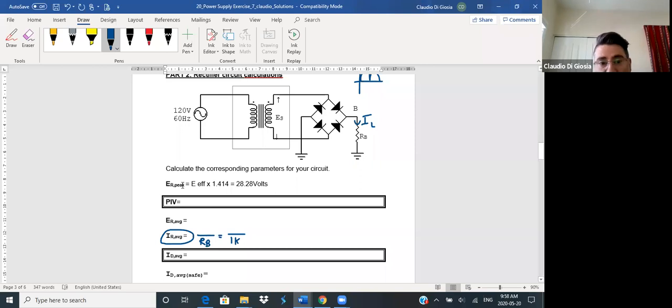So it's basically peak voltage, 28.28 volts. And that's basically when the current's going through and a diode is reverse biased, what is the maximum that it can block? Okay, and then eventually we're going to choose a PIV with PIV safe or merge them together and then go to our charts and compare it to VRRM.